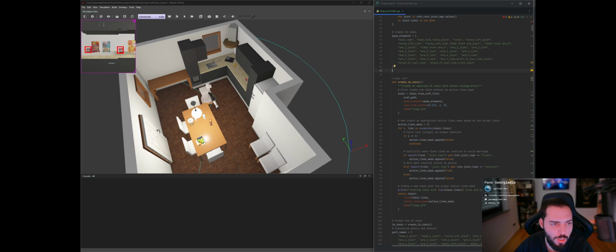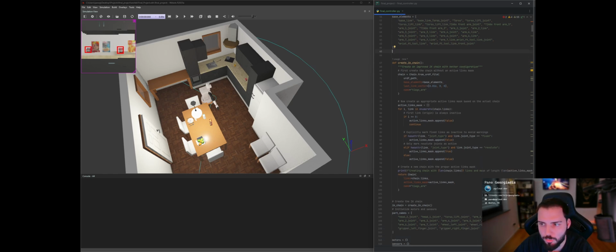It's a very complex mathematical problem, and it's due to multiple possible solutions, or redundancy, because you're working with an arm that I believe is 8 degrees of freedom. To get to one point in a 3D space, you can actually move your arm in multiple positions. Say you have something in front of you like this, well, you can also reach it by going like this. And that's a big issue in calculating inverse kinematics. Also, joint limits must be respected for all the different joints that make up the TIAGo robot's arm. And then singularities that can cause instability, and then the need for a smooth, natural motion. Robots are basically computers. When you tell it to go to a position, it goes to exactly what you tell it to do.